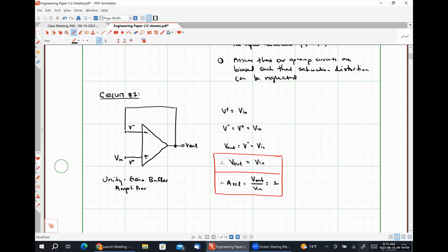And this is an op-amp circuit that is used at the input stage of more complicated systems, particularly when the signal that we are trying to amplify isn't capable of driving a load itself, meaning that whatever source we're using, so that could be some sort of piezoelectric crystal or sensor or something like that, is giving us a very small signal, and we want to make sure that the input resistance seen by that signal is incredibly large so that we don't lose any of the signal itself.